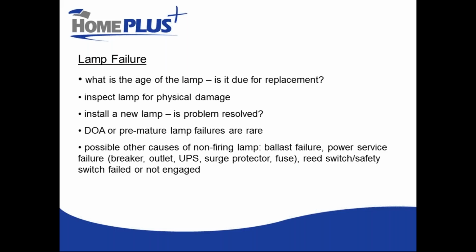On a UV Max Pro, which I'll speak to because a few people have mentioned it already, the lamp harness actually has a pin that extends down from the harness inside a hole in the UV chamber. Inside that hole is where the little reed switch is. So if that little pin does not go in that hole correctly, it won't flip that little reed switch and allow the lamp to fire.